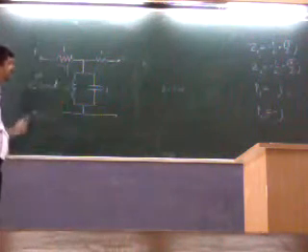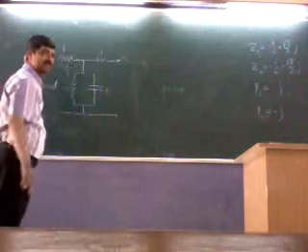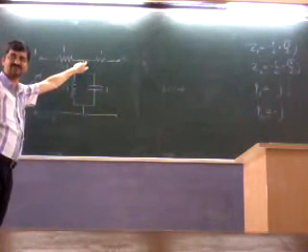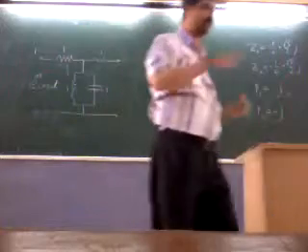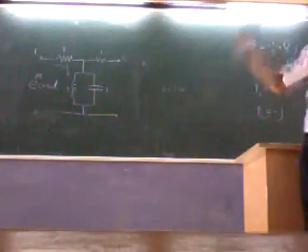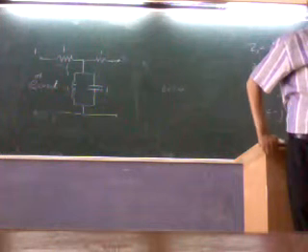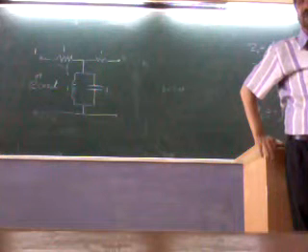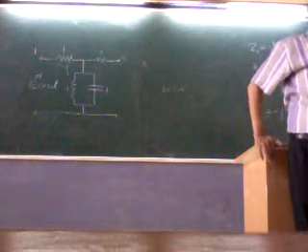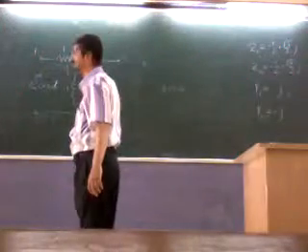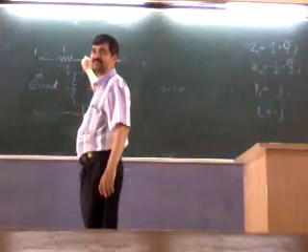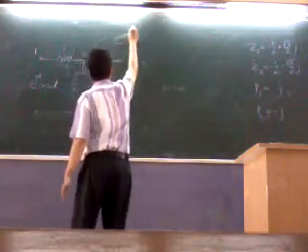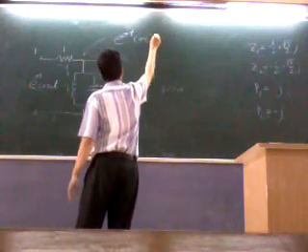So when this current is 0, this voltage must also be the same as this. Are you agreeing now? So we want that when we connect a signal e raised to sigma t cos omega t, we want sigma and omega which give rise to 0 current. Giving rise to 0 current means this voltage must also be the same. So this voltage is e raised to sigma t cos omega t.